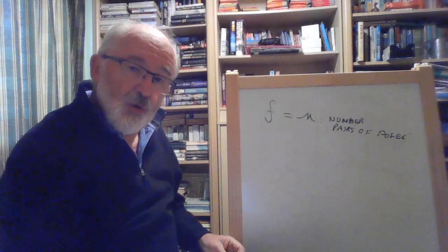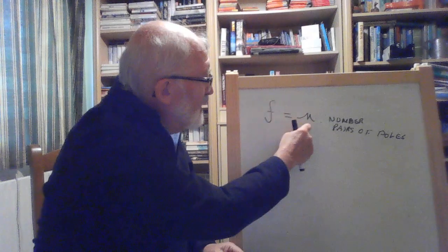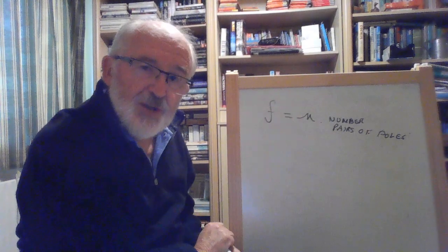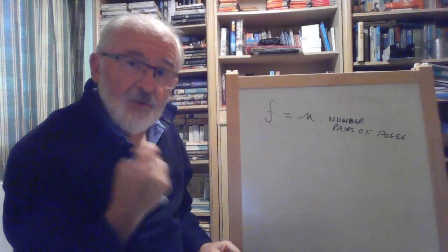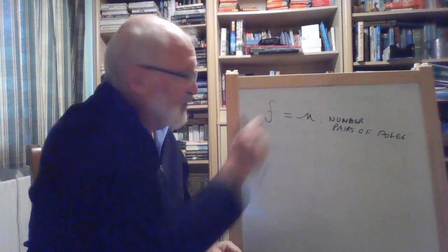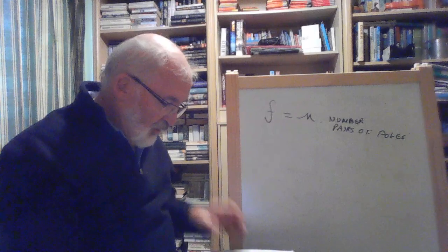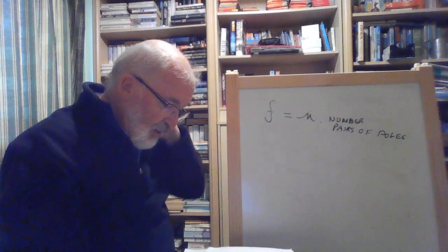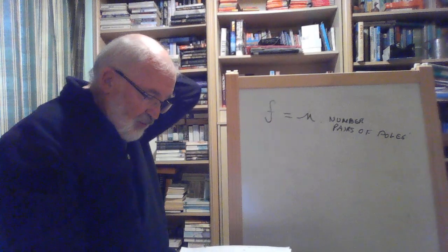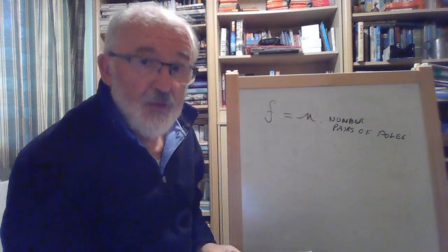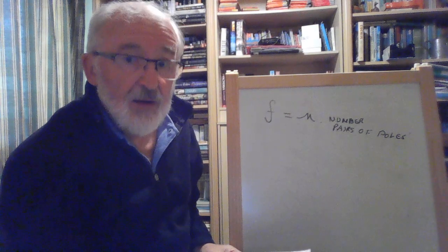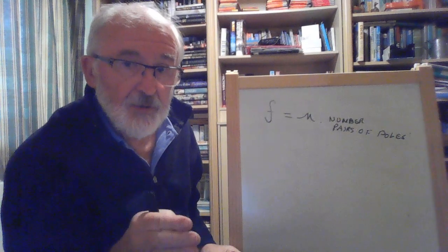Thus, by controlling the speed, we notice that this N, number of revs per second, is common to both the value of the EMF and the frequency. So by controlling the speed and frequency, we can control the voltage output by varying the amount of flux in the rotor. So we want to vary the amount of flux that goes into the rotor.